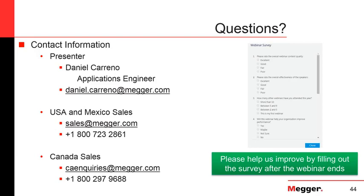So you put your current probes, then you need to calculate or measure the perimeter of the conductor you are testing, multiply that by 1.5, and that will be your distance between your current and potential probe. What it will do is you will measure the voltage drop in the conductors, and that will have a uniformly distributed current flow.